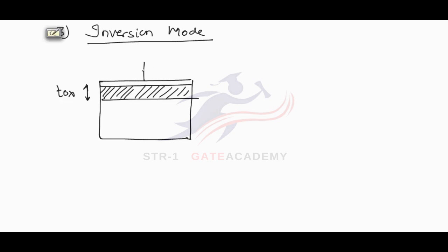This time again we will apply a positive voltage to the gate terminal, but this time this voltage will be greater than this threshold voltage. Threshold voltage, if the applied voltage is greater than threshold voltage, then this applied gate voltage will be sufficient